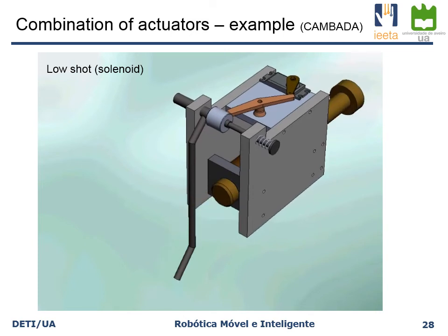As you can see, the plunger is free to move forward and it will kick the ball almost at the actuator. Of course, the speed at which the central plunger will move is dependent on the current that is provided to the coil, but also on the amount of time that current is running on the coil.